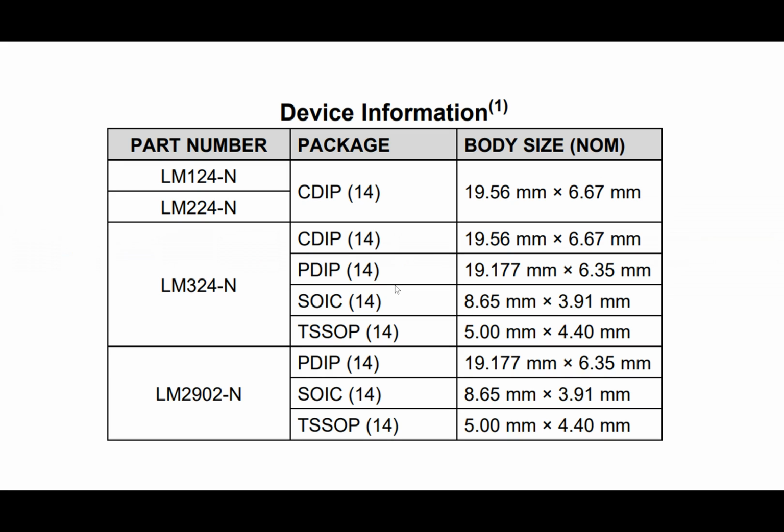The other thing that you'll see Chandan talk a little bit about is how we ultimately choose our packages. So you guys lay out a circuit. You capture a schematic and say, okay, well here's the circuit schematic. And for instance, you may utilize an op amp that's an LM324. And I see that the LM324 has, it would appear, 4 different package types.